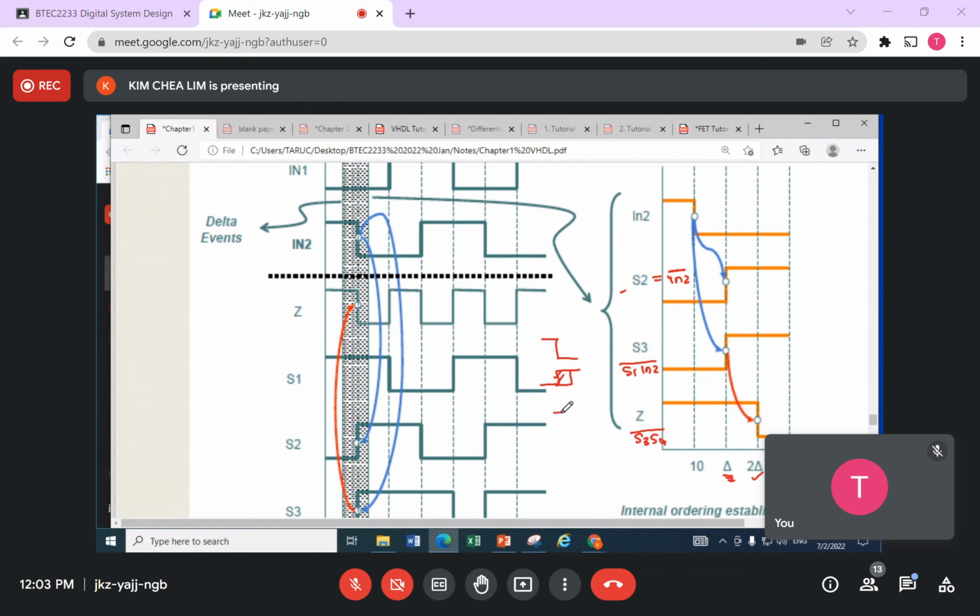And if you have two signals where you want them to perform, don't always make the changes happen at the same time, because at the same time here is maybe a change of 1 delta time, then in your output you may see a spike come out. Why does this happen? The answer is because of overlap of signal. So should I consider this one?